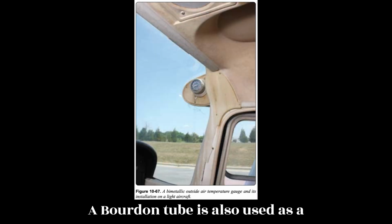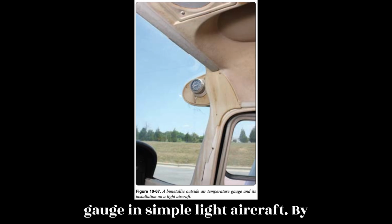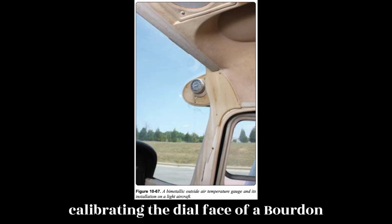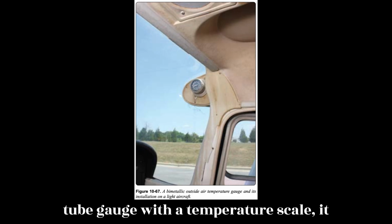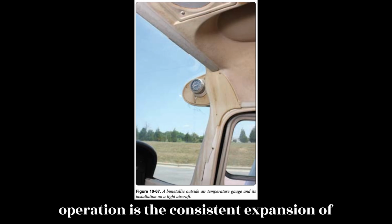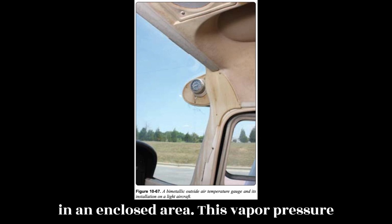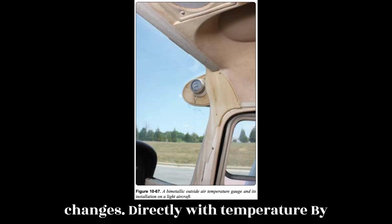A Bourdon tube is also used as a direct reading non-electric temperature gauge in simple, light aircraft. By calibrating the dial face of a Bourdon tube gauge with a temperature scale, it can indicate temperature. The basis for operation is the consistent expansion of the vapor produced by a volatile liquid in an enclosed area. This vapor pressure changes directly with temperature.